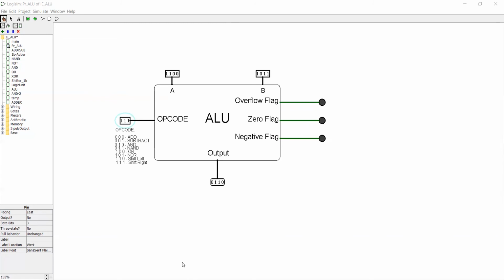I have only designed a small ALU, but a similar procedure can be used to design entire CPUs. One of the great features of Logisim is the ability to prototype with already built-in gates and shifters, and then use that same functionality to test my own parts. The subcircuit feature of Logisim allows me to reuse circuits instead of designing everything from scratch, hence giving the hierarchical circuit design that is used in a lot of industry projects.